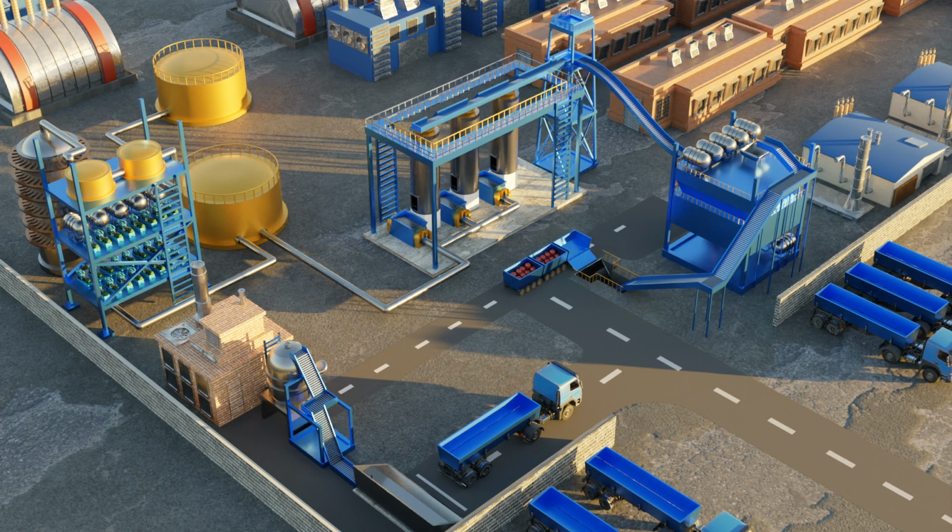In the palm oil production industry, the fresh palm fruit bunches are transported by truck and discharged to the storage area, where the palm fruit will be loaded into the sterilizer to be sterilized under certain temperature and pressure. After that, it will be discharged from the bottom screw conveyor and transported to the thresher drum, where the empty fruit bunch and fruit will be separated.